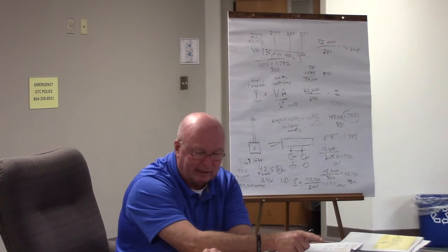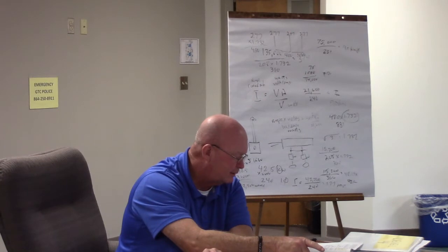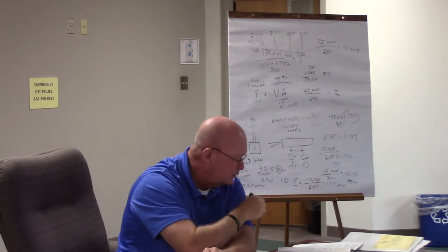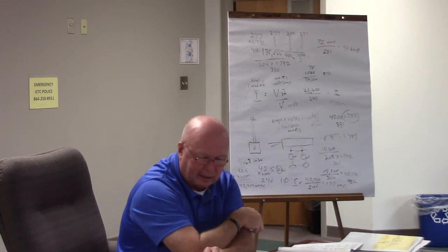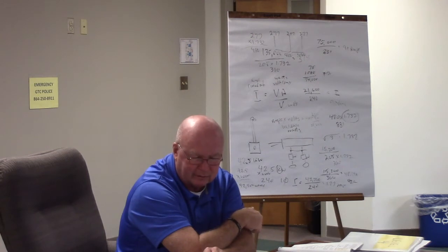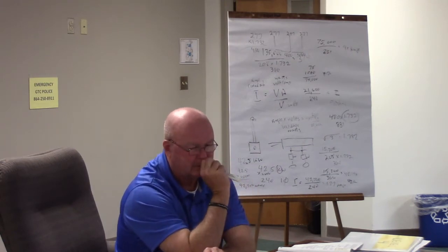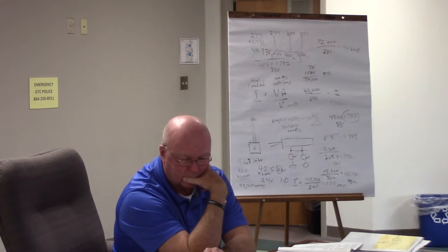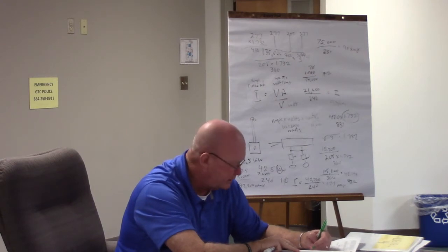Because if not, we have to go back. I'm stopping myself for a minute, asking myself, why number 1, why not number 2? I think I disagree with that. If not, then number 1 would be required, where I really think, if not, we'd drop back to the 60-degree column. And number 2 is rated for 95 amps, isn't it? So I disagree with that. I'm going to question that right there. I think it's actually number 2.